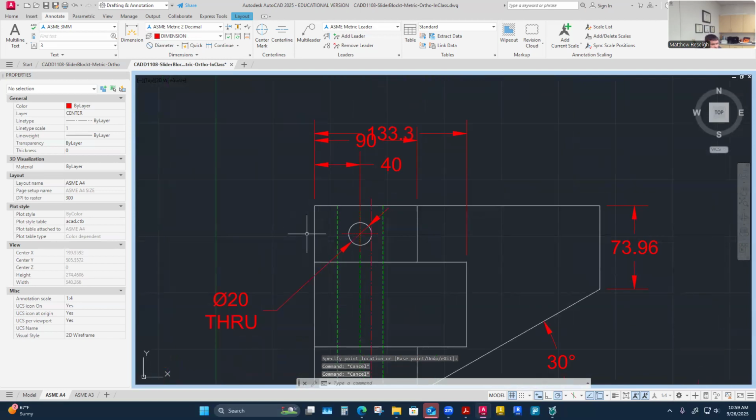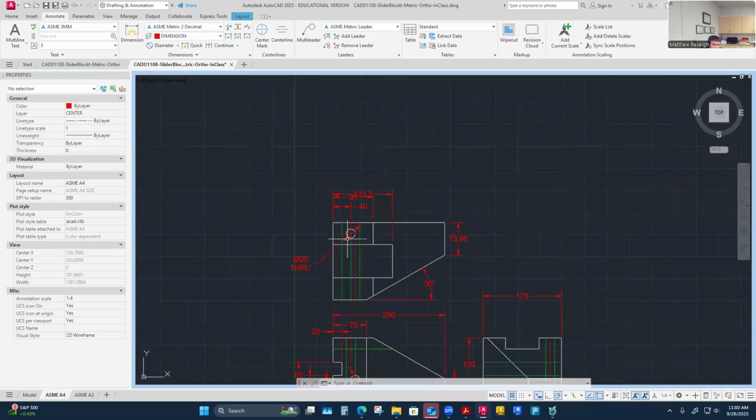So before I would put in the next location, what my mind would do would be like, have I already kind of established a good datum from front to back? Have I pulled any dimensions from either the front surface or the back surface? Well, in this view, I've actually pulled a dimension from the back surface. So I've kind of already started a control hold on this a little bit. So maybe that's the best. I'm kind of establishing the back as a sort of datum. I'm definitely establishing a point to pull dimensions from. So should I pull this dimension from there or should I pull it from here up?